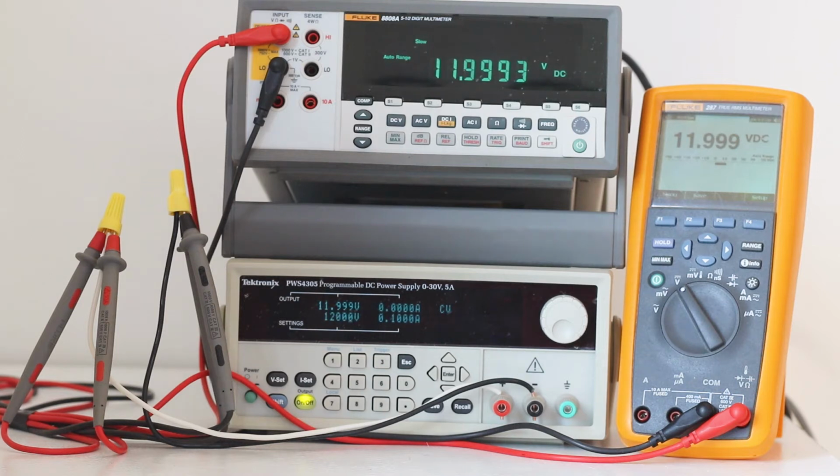Consider, for example, a digital voltmeter that begins at 0 volts and extends to 1,000 volts, with a digital readout that displays the number of volts in steps of 0.001 volt. The resolution then is a thousandth of a volt, but the accuracy is unknowable unless there is an external standard to which it can be compared.